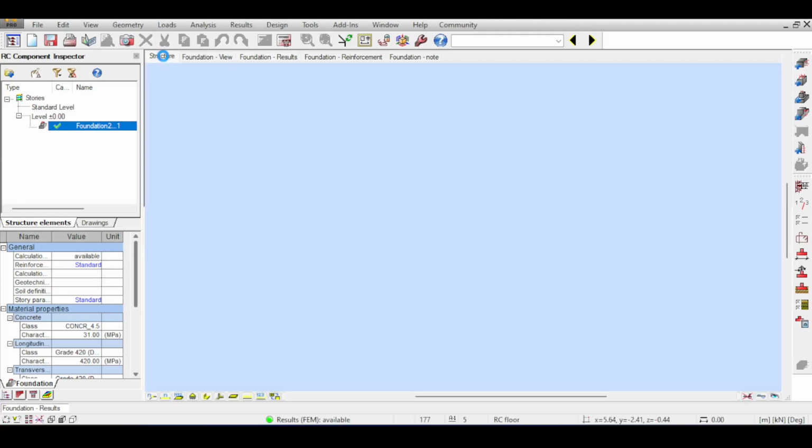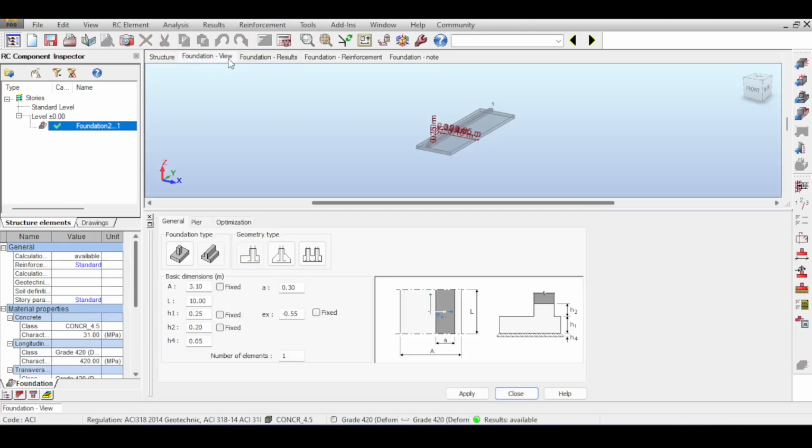The second thing I got was feedback from our dear subscriber Donald Khanye, who says that the dimensions seem to be off, and he's right, by the way. The dimensions in the first iteration, without all this factor of safety stuff, seemed to be off. The length of the foundation from the side, this distance, was too much, and in comparison with Braja Das's recommendation, it was totally off the charts, and I agree with him. The reason why this was so was because I wasn't considering the soil above the heel, because I wanted to make a simplified retaining wall.